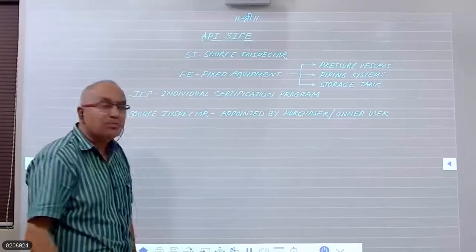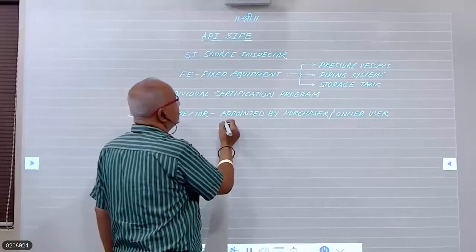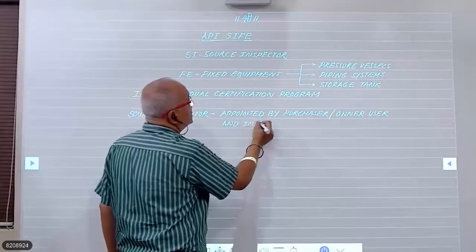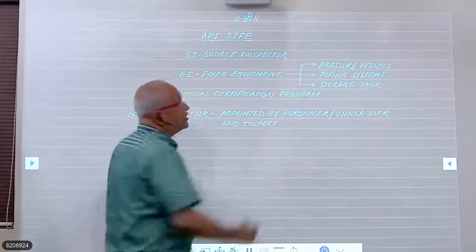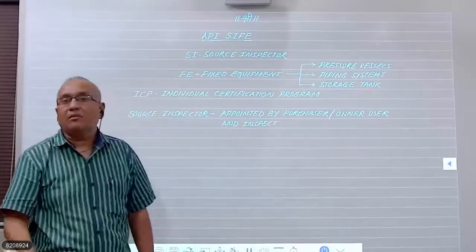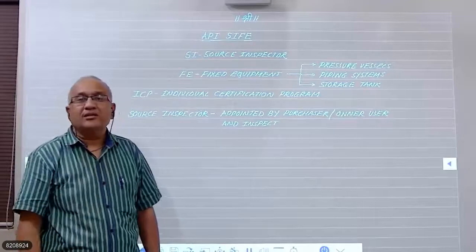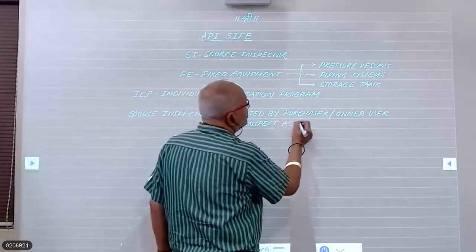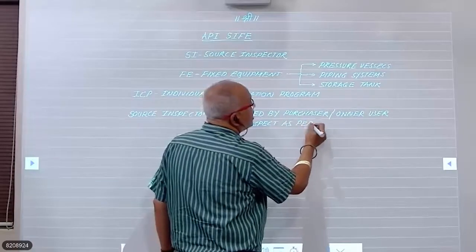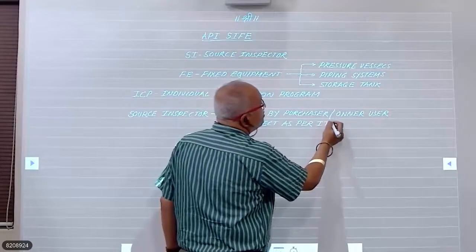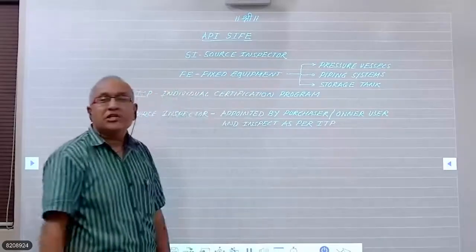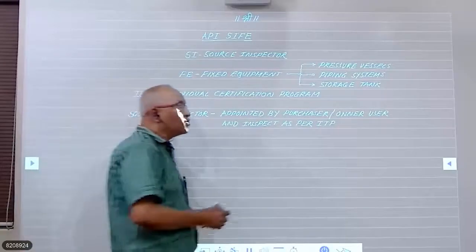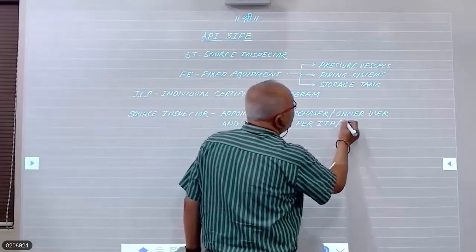and inspect either pressure vessel or piping systems or storage tanks as per the ITP, inspection and test plan, or sometimes it is also called QAP.